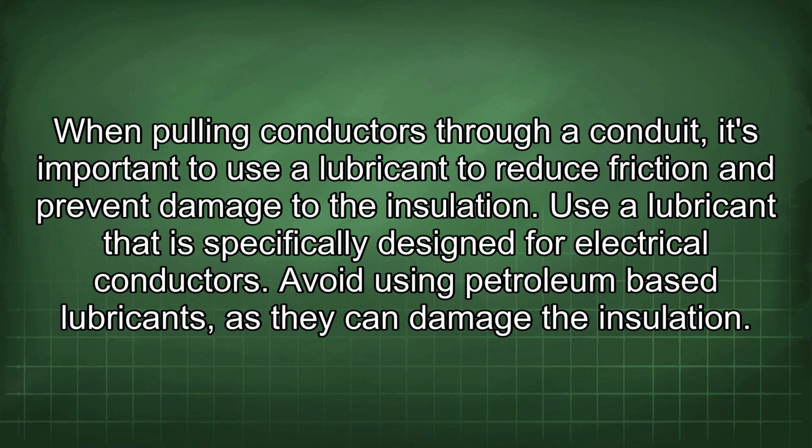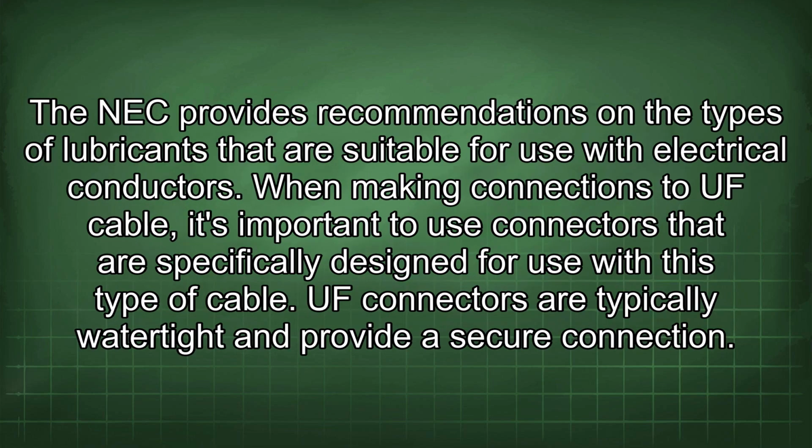When pulling conductors through a conduit, it's important to use a lubricant to reduce friction and prevent damage to the insulation. Use a lubricant that is specifically designed for electrical conductors. Avoid using petroleum-based lubricants as they can damage the insulation. The NEC provides recommendations on the types of lubricants that are suitable for use with electrical conductors.